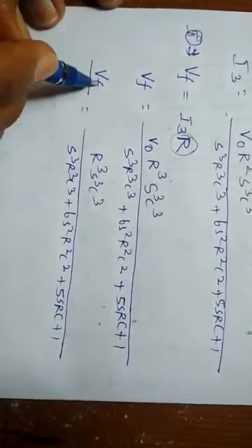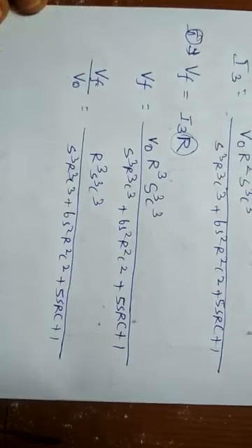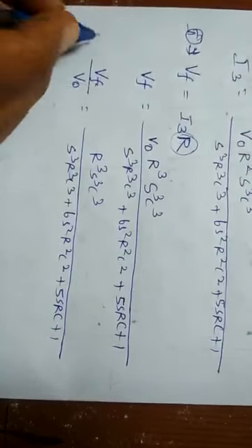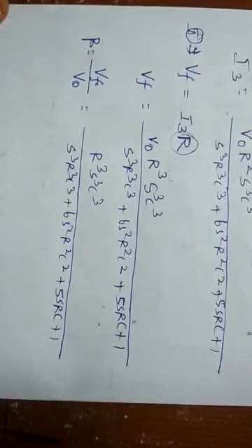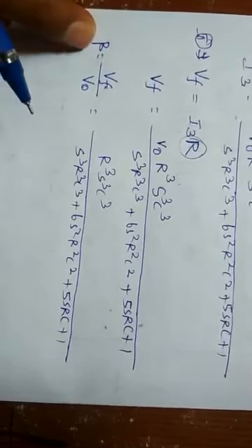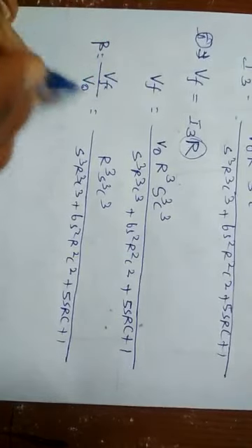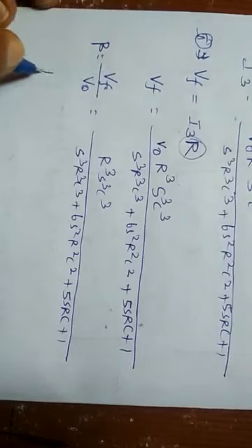So the Vf is the output from the feedback network and V out is the input to the feedback network. So output of the feedback network divided by input to the feedback network is the gain of the feedback network, and we have already named this as beta. Beta is Vf by V out. So hereafter we can use this beta for Vf by V out.